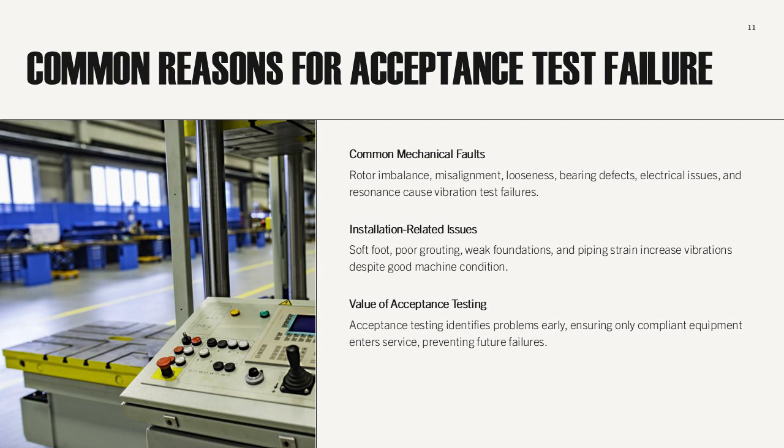Installation-related issues are also a frequent cause of acceptance failure. Soft foot, improper grouting, inadequate foundation stiffness, and piping strain can significantly increase vibration levels even if the machine itself is in good condition. Acceptance testing helps distinguish between machine-related and installation-related problems, allowing corrective actions to be targeted effectively.